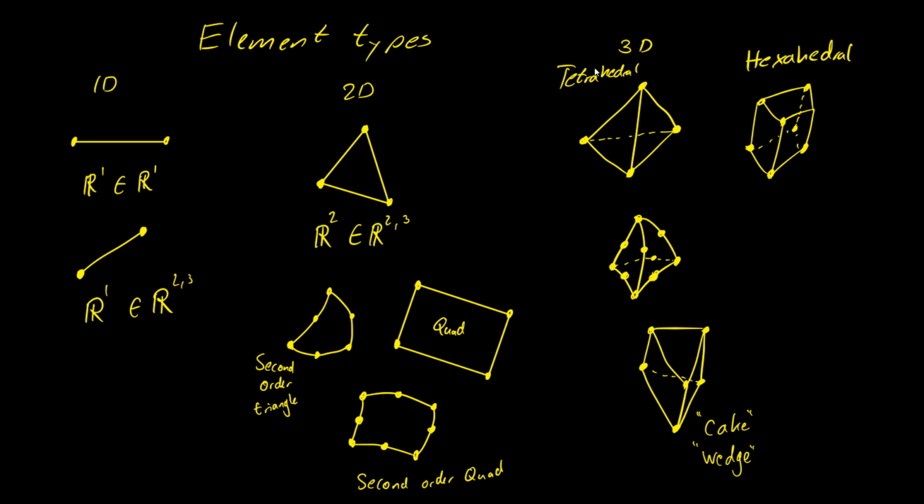It's a huge amount of different elements, and each has corresponding basis functions attached to it, and each really has a corresponding quadrature scheme attached to it. Usually we can use the Gauss function that you have seen, but there are often more elaborate Gauss quadratures. Remember, we are trying to integrate with as few Gauss points, or rather integration points, as possible. That's why there's a lot of research which is happening and has happened in that area to sort of integrate this stuff exactly using lower order quadrature.